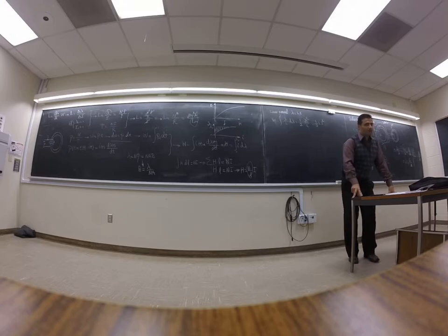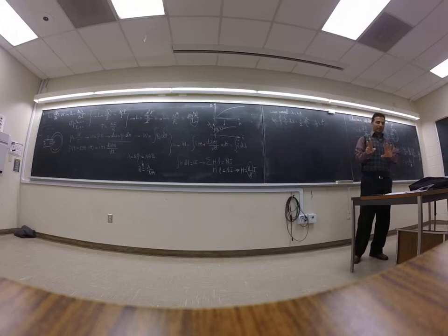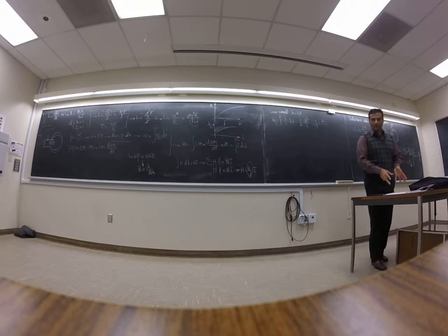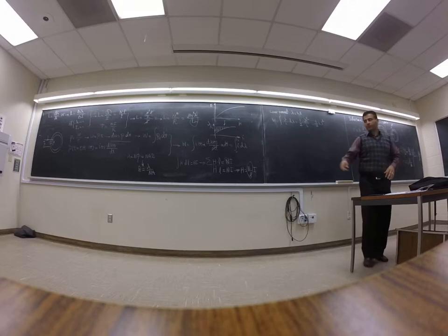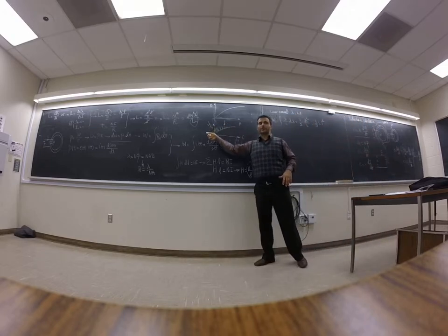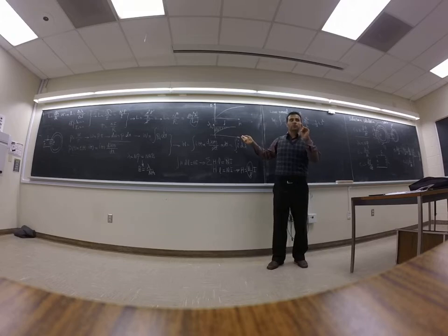So I'm going to give you lambda I, but keep this one in mind. I'm going to sit in my lab. I'm a manufacturer. I design one inductor here, and I come up with this lambda I. I measure the length, turns, and all those kind of things. I say, okay, this is your lambda I. Now, are you going to use exactly the inductor that I have? Most probably not. For example, the one I designed in my lab is 1 millihenry or 2 millihenry, whatever. You want 10 millihenry. You want 0.1 millihenry. So you don't want this curve. This curve depends on the physical dimension. This is what you design.